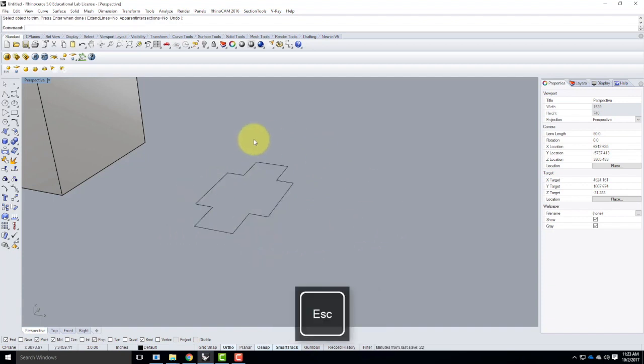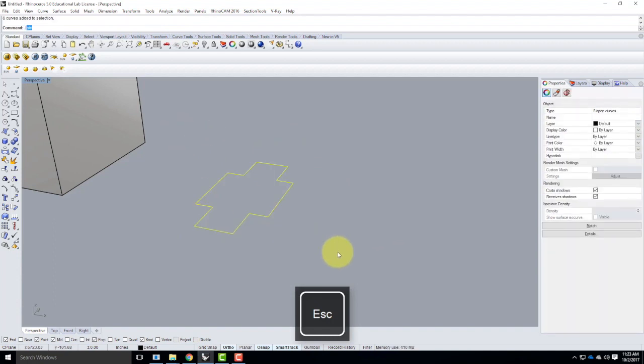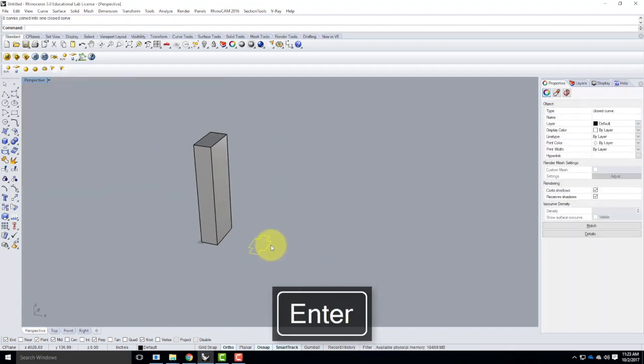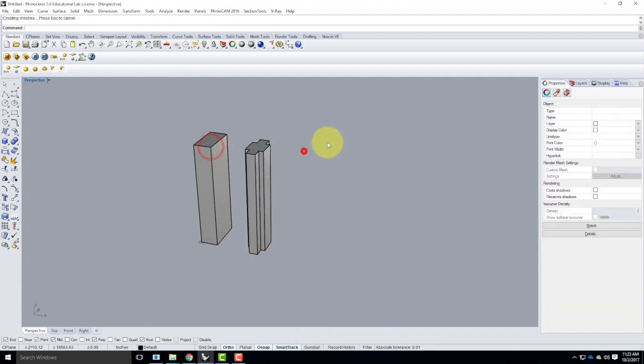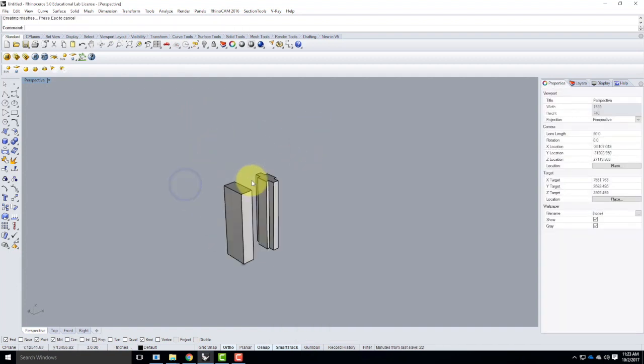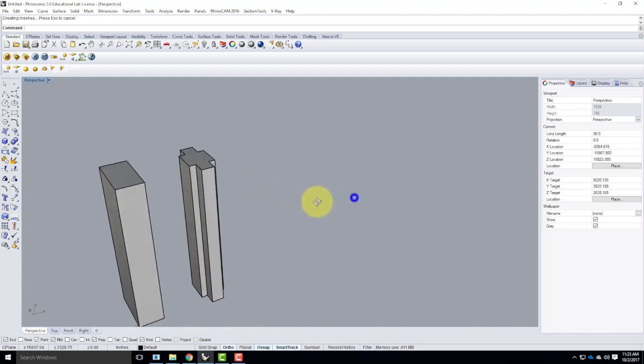All right, so I've got that shape this time. I'll join it, and then I'll extrude the curve. Extrude curve. Remember, we do want it to be solid, so solid should be set to yes, and we'll make the height the same at 600 feet. Okay, so I made the building a little bit more complicated just by doing an extrusion.